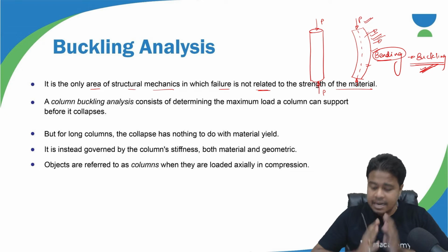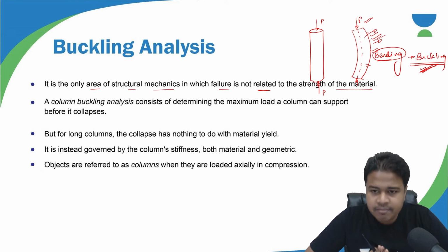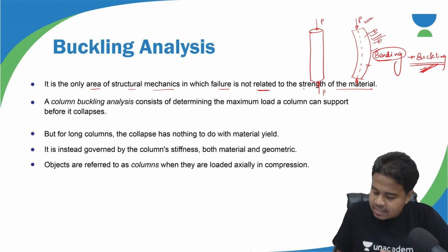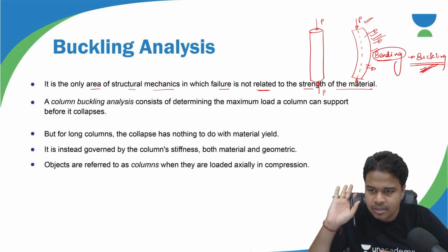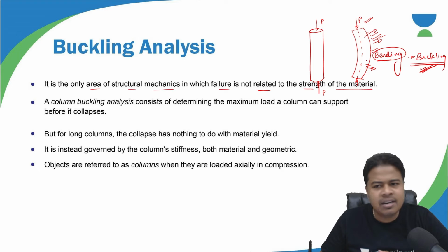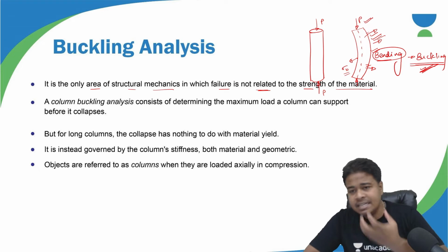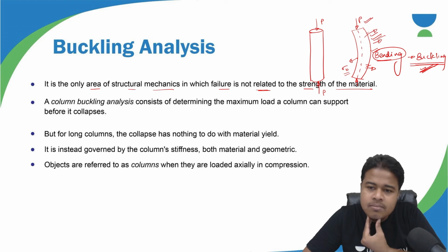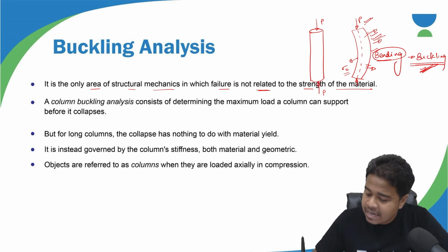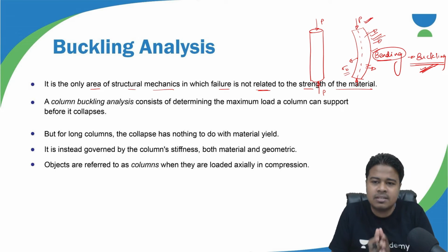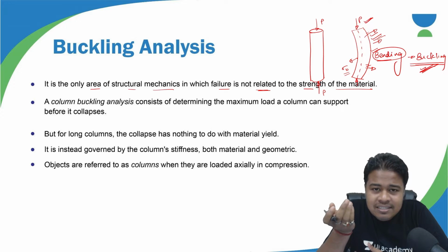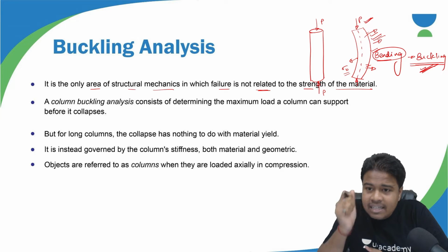Okay, so that's the very important part which I wanted to convey. So obviously, due to bending, suppose this column has started buckling, so some sort of bending stress will occur here. If bending stress occurs onto these columns, that bending stress plus the axial stress which is coming, that combined total normal stress must not exceed the yield stress.